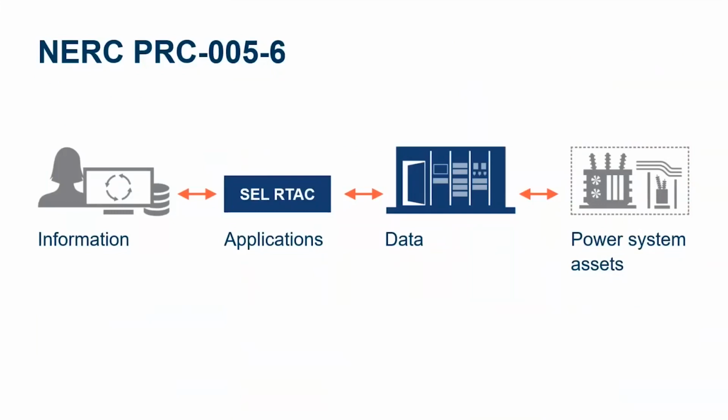Using the SEL's RTAC, you can build an automated system that will verify commissioned IED settings and firmware configuration, generate automated reports for both local and remote access, assess the health of breakers and trip coil assemblies, verify CTs and PTs with continuous IED measurements, verify the communication-assisted protection channel integrity, monitor IED diagnostics, and so forth.